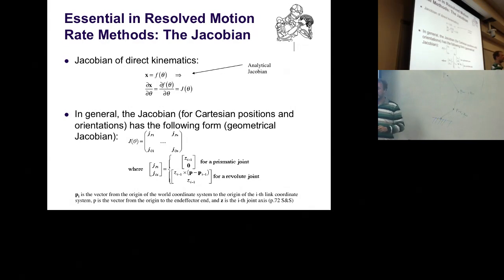Good. Now figuring out how every degree of freedom can contribute to the motion at the end effector is equivalent, as it turns out, to figuring out what is called the geometric Jacobian. That's a nice, easy thing to think about. So let's take, for instance, this degree of freedom down here. Now freeze this one and this one, okay? They are stiff now, forget about them. If I move this guy, how can this point move? Well, it's very easy to figure out. So we just create an approximately straight line, as much as I can do this, between this point and this point. And then I know if I move this degree of freedom, it can only move in this direction. Okay? Make sense? Not a big deal. Cool.